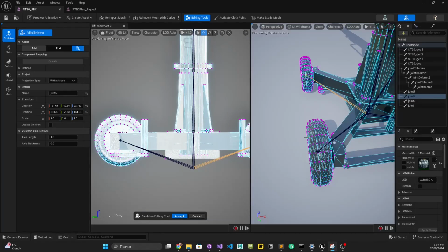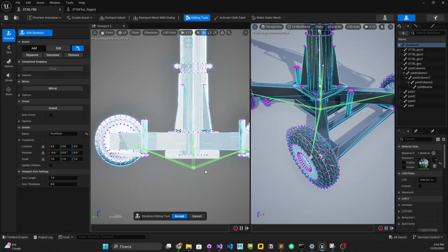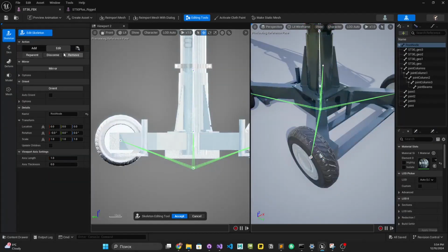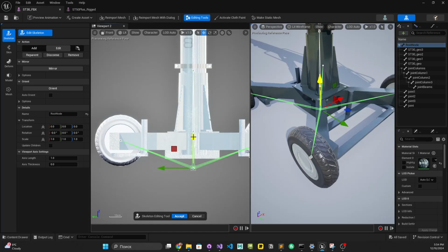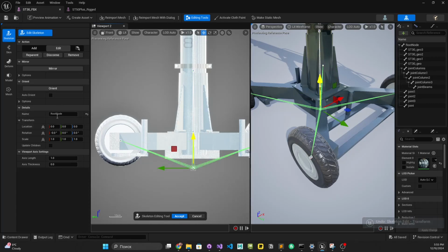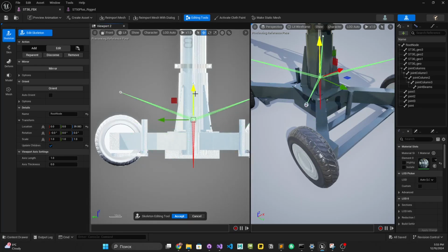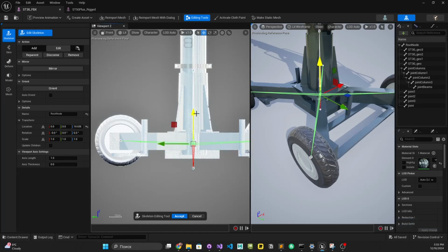Yeah, so let's repeat this. So first of all, the root joint. When we are in edit mode, we should be able to just move it up. So let's select the joint and try to move it. By the way, I just want to highlight that you have this mode to update children. If you use this mode, then you offset the whole skeleton, right? So we don't need it right now, so we could just put it inside the base.